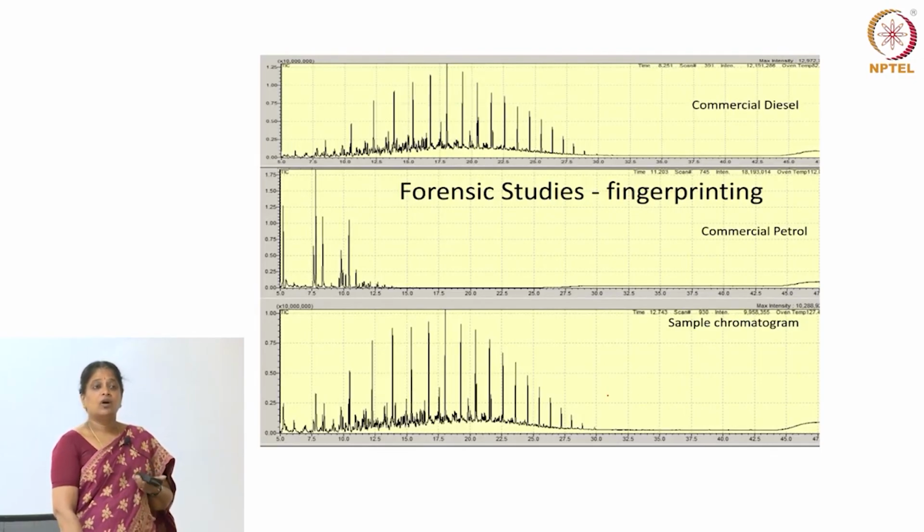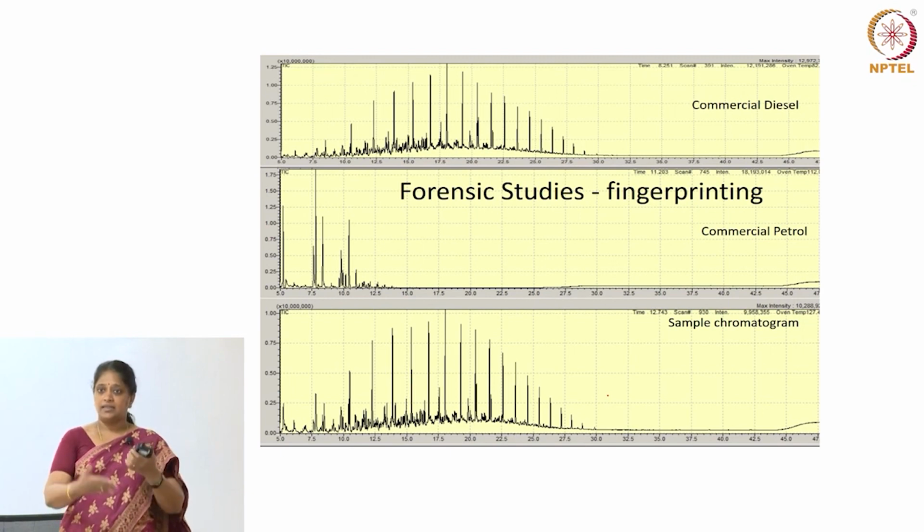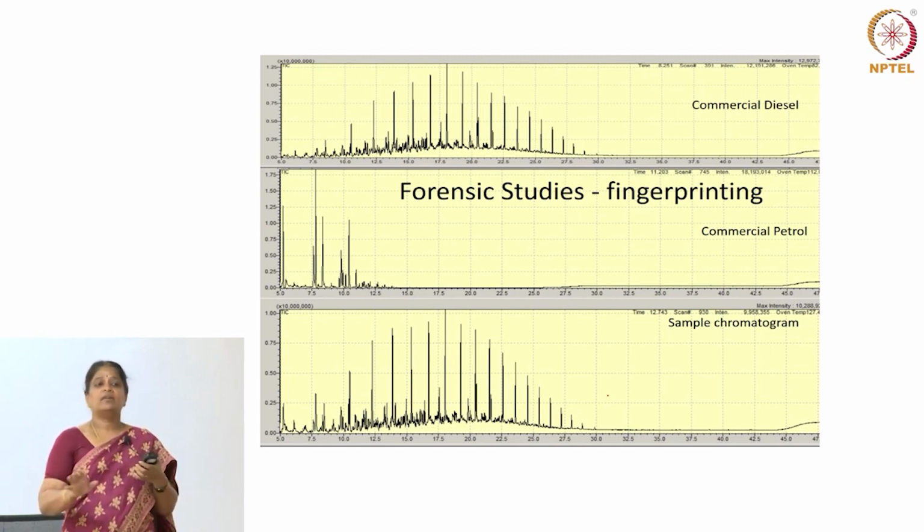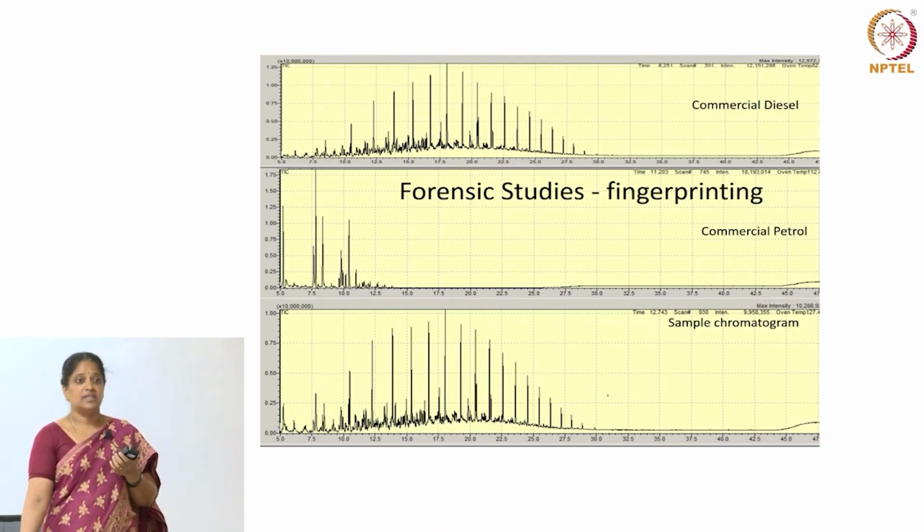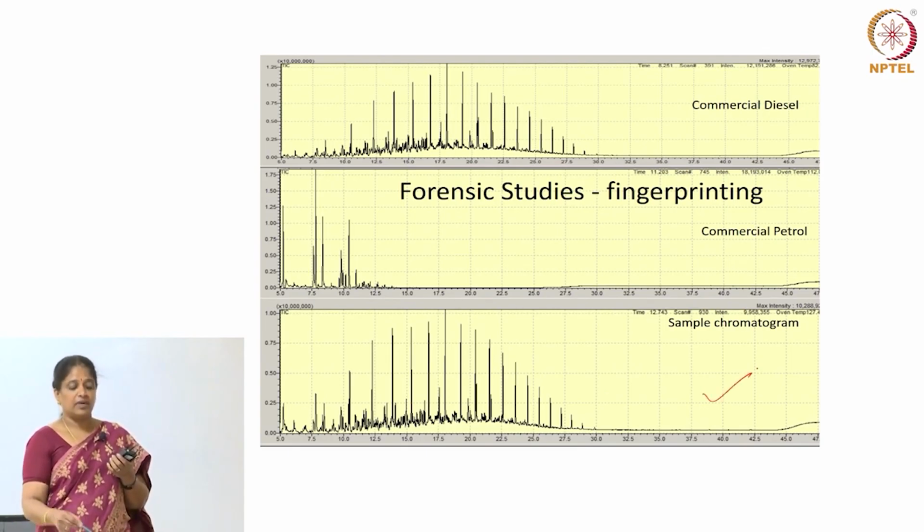And so, we do some forensic science also, because when there is a spill and there is no industry nearby, everybody will say it is not mine, right. People were trying to point fingers at a petrol bunk, at somewhere, they did not accept that it was a pipeline spill. So, we have to do forensics to see what the sample is. This was the fingerprint of a GC, gas chromatograph, of the sample collected from the site.